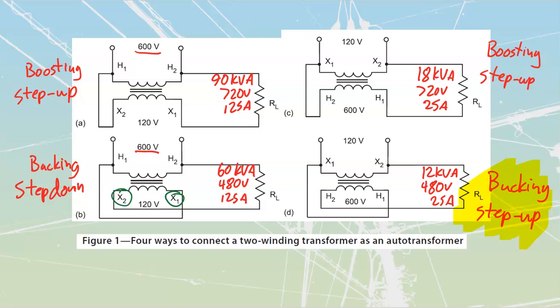out in the trade that are just going to tell me that we need a boosting transformer. No, what you're looking for is a step-up transformer there. That's what you meant to tell me, but you just said boosting and bucking because you vaguely remember those terms from some time back in second year. This is the point where most of them pick up those terms and just misapply them.